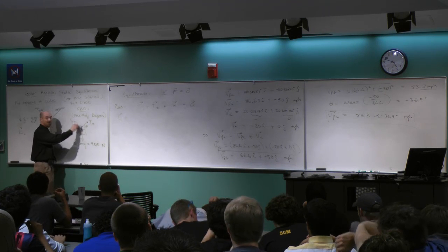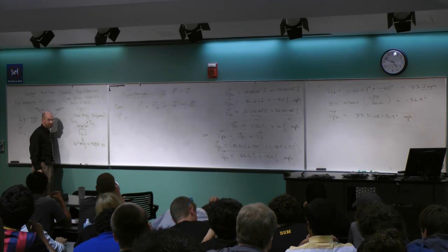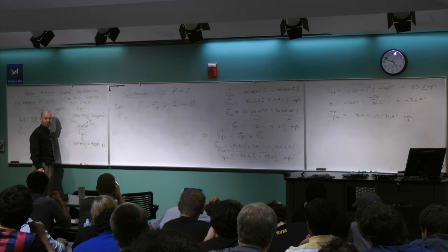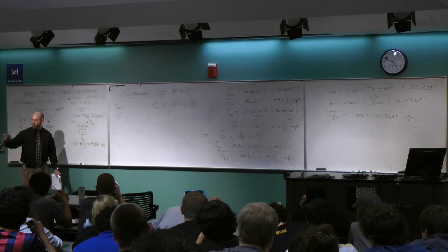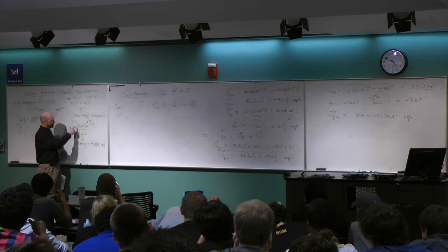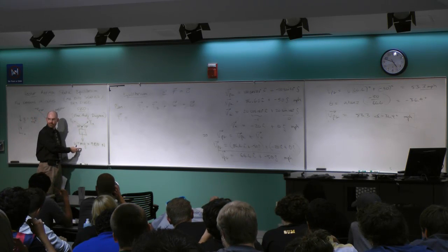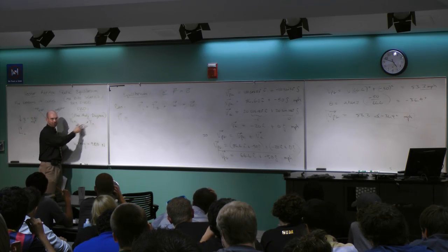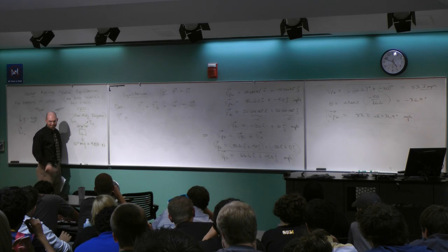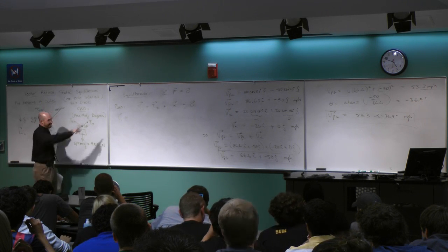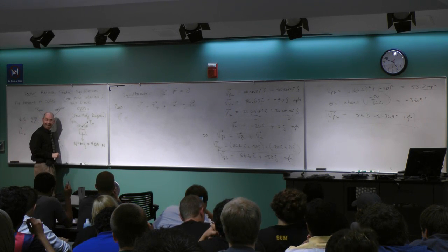I would always label it like that. T1 is the magnitude of this vector. It's the hypotenuse. Do I know what it is? I could deduce it, right? The calculator punch I was talking about. Are you ready? Here it goes. Y component of this and this has to add up to that, right? And there's 2 of these, so it's 2T1 times the sine of 45 equals 9810. Solve for it, you're done. Okay? That's it.